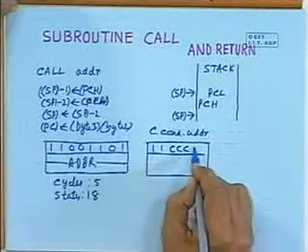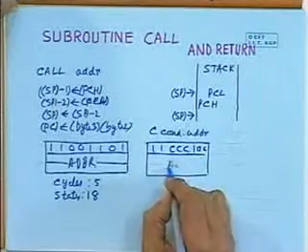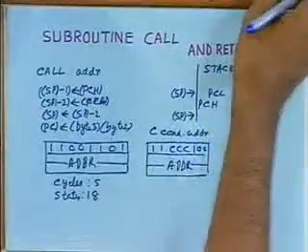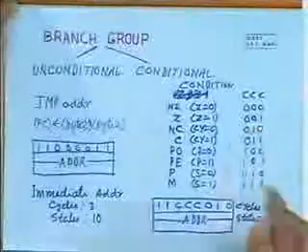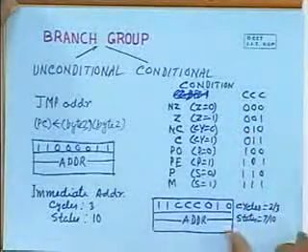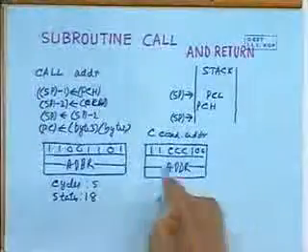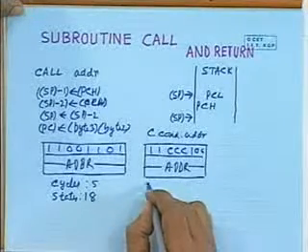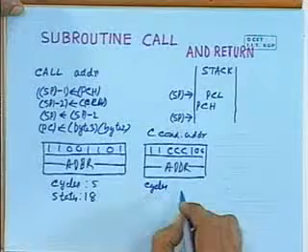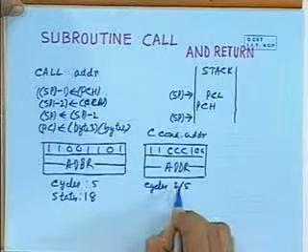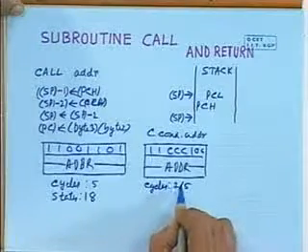Here is your CCC, and then the address. So the same conditions which are used in case of your unconditional branch are used in case of conditional subroutines. So the total cycles required is either 2 or 5. So you see here again the time required is different.